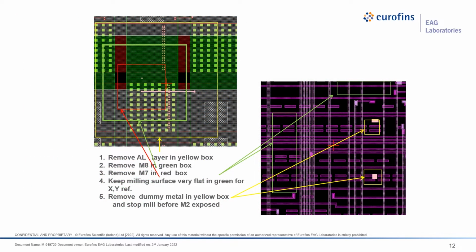In the old days, back when I first started doing FIB, we simply tried to find a location and we dug a very deep, very narrow hole and tried to make connections. We used to call them oil wells. We would go drill an oil well. Those are not great. They don't have a super high success rate. But now, part of the reason that EAG is so good is we have some people that can go in with the GDS2 files and locate and plan out a strategy